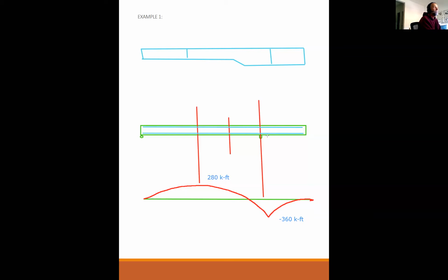Once you have your depth determined by the practices and the methods that I've given to you, once you determine what that depth wants to be, it's going to be the same depth everywhere on the beam, but in other locations, you can use less steel. That's how those work. So like for the positive design, if I use, let's say 3 rebar, and then the negative I use 4 rebar, that would be okay as long as it met the requirements.